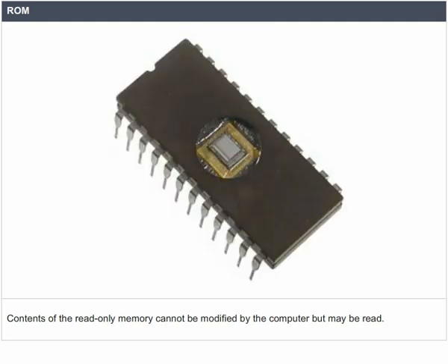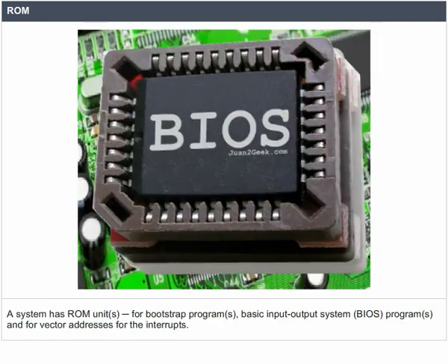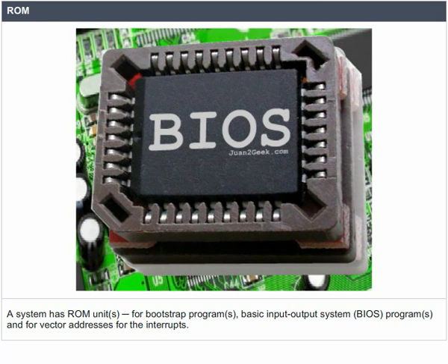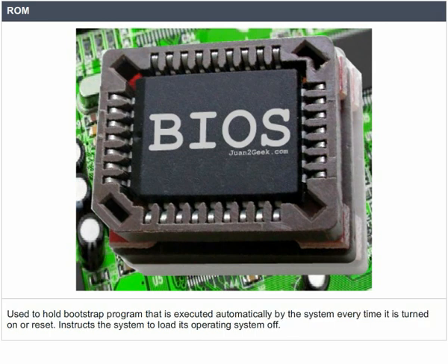ROM. Contents of the read-only memory cannot be modified by the computer but may be read. A system has ROM units for bootstrap programs, basic input-output system, BIOS programs, and for vector addresses for the interrupts. Used to hold bootstrap program that is executed automatically by the system every time it is turned on or reset. Instruct the system to load its operating system off.